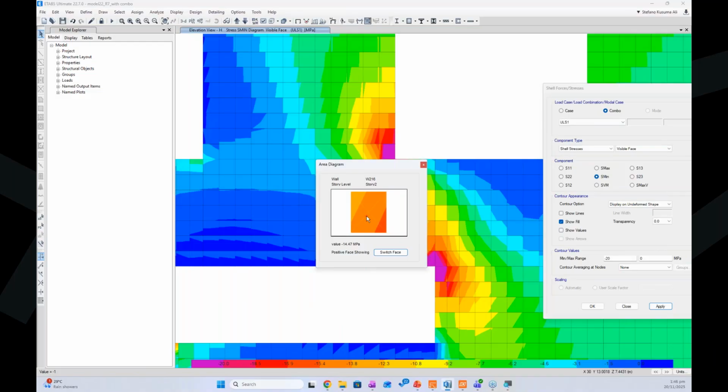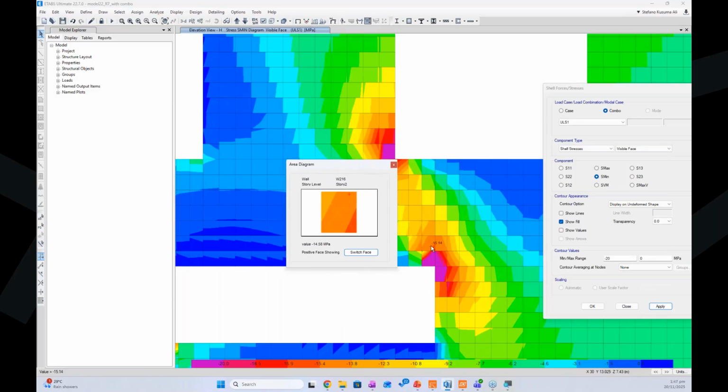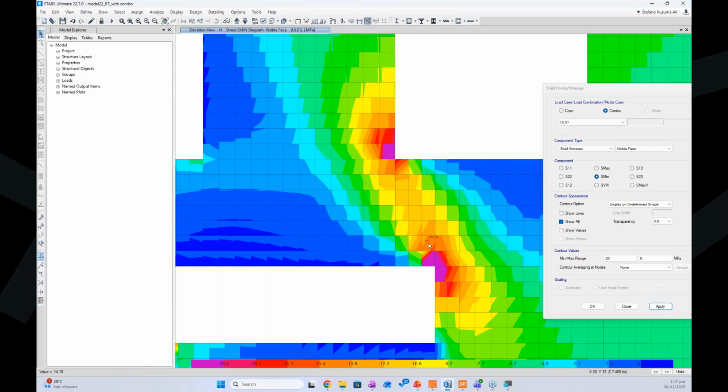Referring to our fck, let's say we are using a 30 MPa concrete capacity and we divide by the safety factor of 1.5. It comes out to be around 20 MPa capacity, based on stress alone. So I would say this wall thickness is still okay, and you can still use this wall with this thickness based on this.